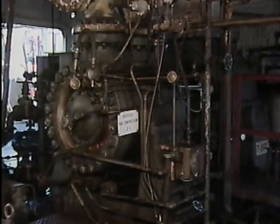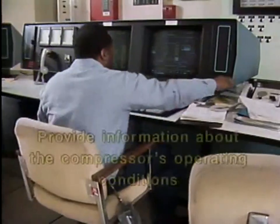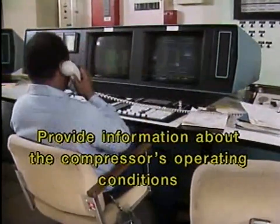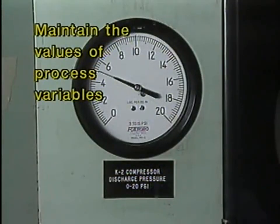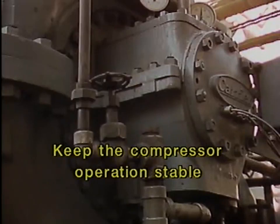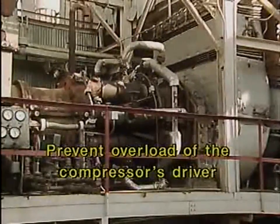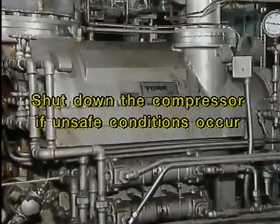For example, these devices allow the compressor to be started or stopped. They provide information about the compressor's operating conditions. They maintain the values of process variables, such as the compressor's discharge pressure. They keep the compressor operation stable. They prevent overload of the compressor's driver. And they can shut down the compressor if unsafe conditions occur.